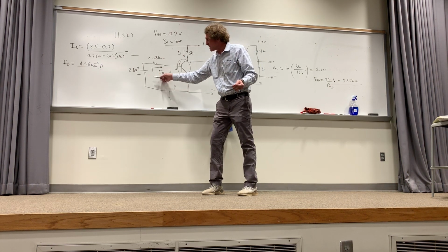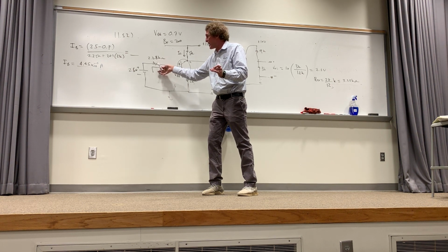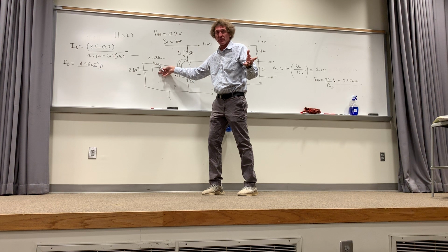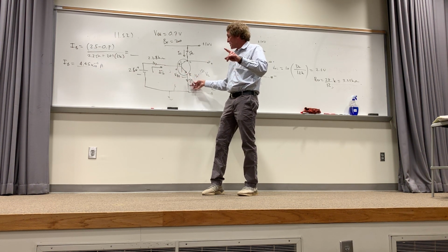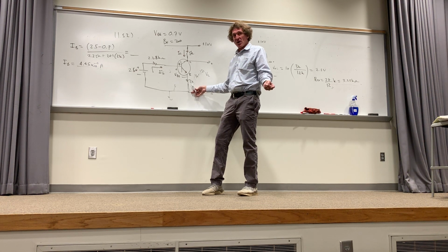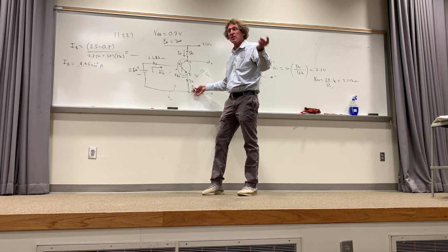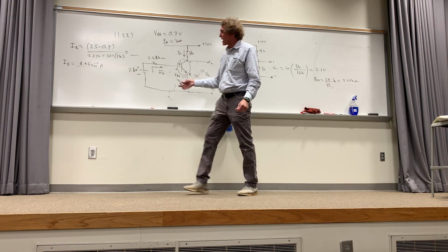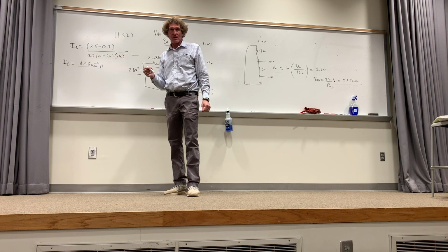When I did that, I said an increase of this voltage, which is VBB, minus IB times this resistance, which I called RB, minus this voltage VBE, and then minus this voltage drop. Well, that voltage drop is going to be that resistance, 2K, times the emitter current. And the emitter current is beta forward plus 1 times IB, all right? And that's the reason that beta plus 1 is right there, 201 times 2K. So it amplifies it. In other words, it enhances the value.